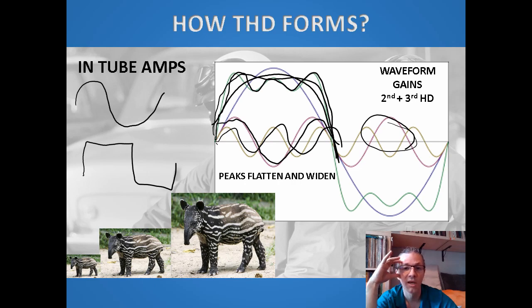So when you have this distortion and your sine wave almost becomes a square wave, of course with ripples here, that's already gross clipping and gross distortion. That's when your amp sounds like something dying, and usually long before that we do not push our gear to reach that stage.